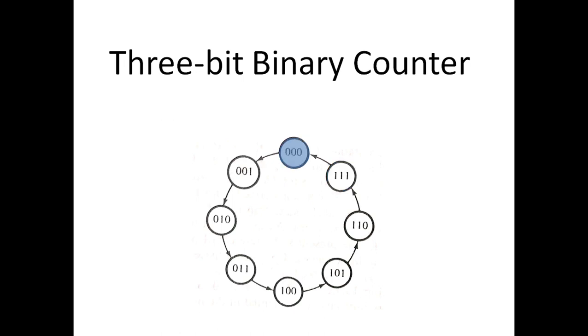And then it repeats back to the initial state of the sequential circuit. So we have 3 bits, and the values of these 3 bits change in ascending order from 0 to 7. Each sequence represents the digits of the decimal system, 0 to 7, and then it repeats.